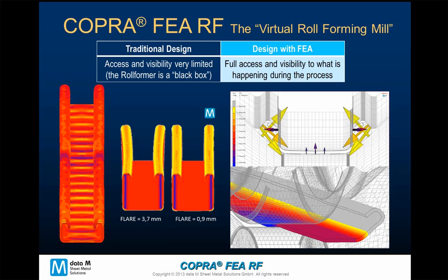We can determine the forces acting upon the strip, any elongations that could be caused by these forces, and we can obtain a true three-dimensional view of material behaviour actually taking place during the forming process. We can even quantify these problems, which normally are only encountered at the machine. We can establish what's actually causing it, not just surmising what is happening. So we can solve these problems based upon facts.